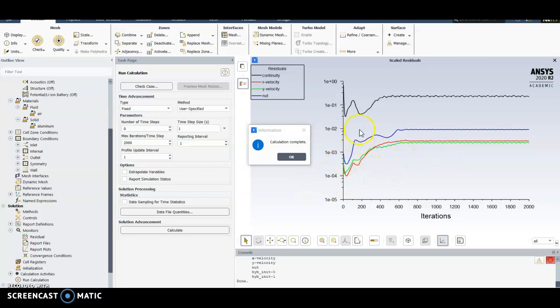But anyway, to improve this, you need to improve the mesh. It's most often to do with the mesh, I believe. You need to improve the mesh and make it more structured. In our mesh, you could see it didn't look as good, right? Some areas are denser than others. You want it to grow evenly outward, so you want a much better mesh.